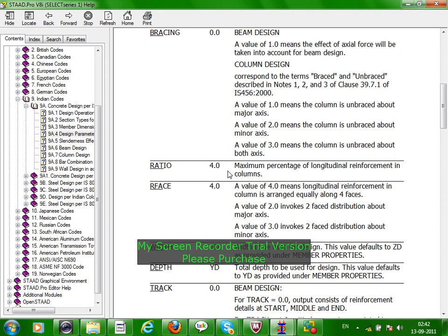That is the limit state approach. So it will not automatically consider double reinforcement design. For that you have to make a trial and error. Remember that.